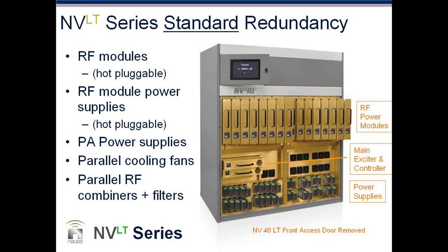Right. If you look at the topology of any solid-state transmitter, the RF amplifiers are obviously the heart of it, the energy being pumped out to the antenna. So the NV LT has a number of those modules. They're 2.5 kilowatt modules in parallel in a hybrid combined fashion. They are hot pluggable, which means you can disable the module and pull it out without turning off the transmitter. You don't interrupt the power. Same with the power supplies.